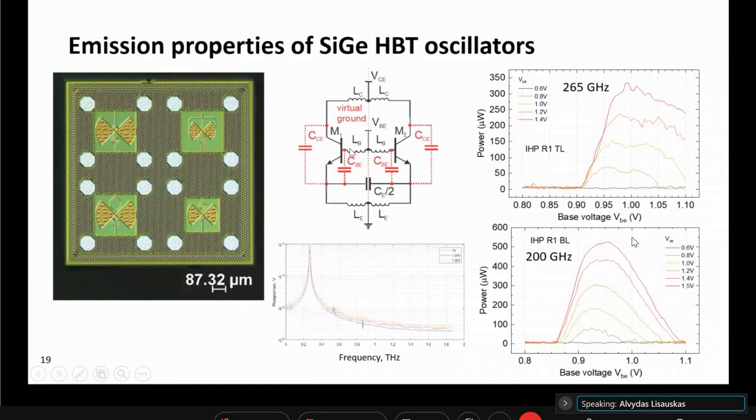That's an oscillator. It's actually the same Colpitts here. Only the field effect transistors have been exchanged for bipolar transistors. So, a pretty simple design. And by now, FBH and many other teams are shifting from the classical textbook push-push into the Colpitts configuration. It seems to be really the winning configuration at the highest frequencies. There's still art left in how one implements high frequency components, and as you see here, one can do it in many different ways.